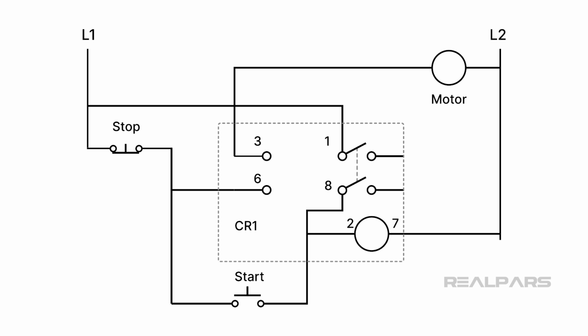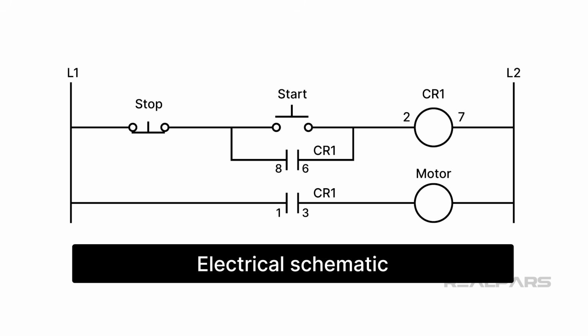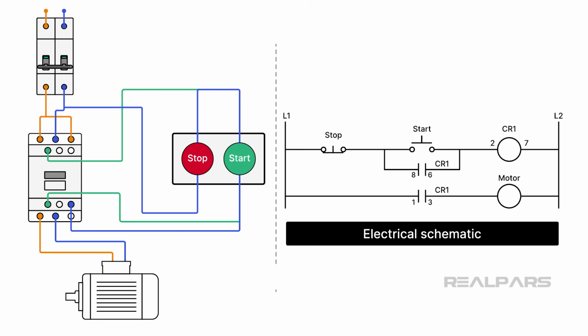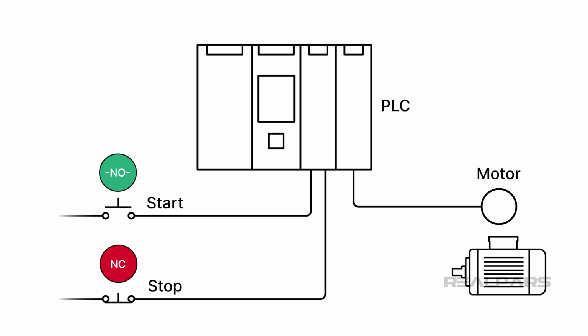Looking at a different schematic version of the same electrical circuit, the relay ladder version is the clear winner for interpreting circuit action. Okay, let's forget about that ugly second schematic and focus on the relay ladder version. We said earlier that the stop switch, start switch, and control relay were hardwired together to operate a motor. Making changes or replacing defective components often required cutting wires or, at the very least, removing them from terminals and rewiring the entire system. PLCs came along and made things so much easier.